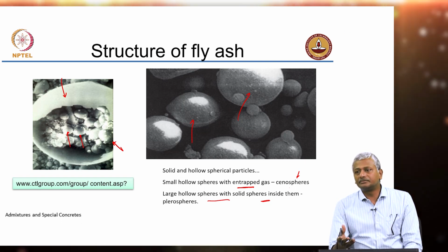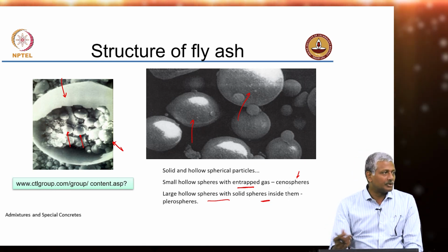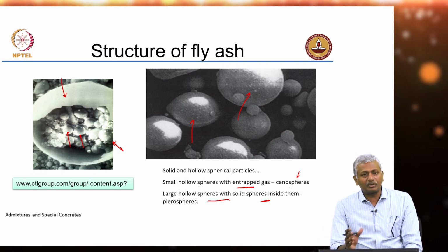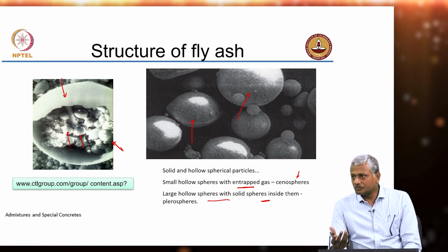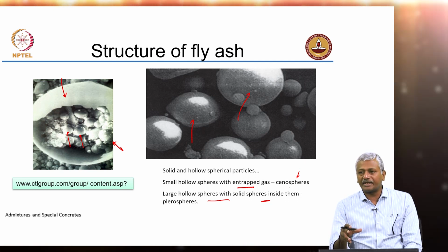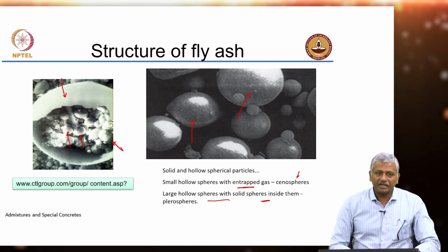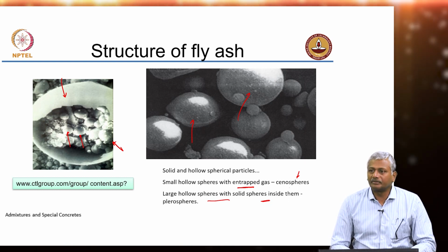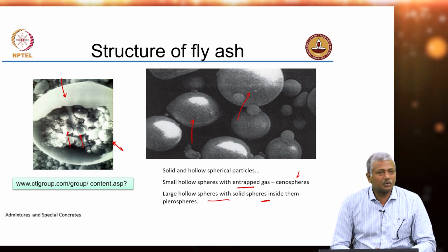What would that do? It would go against your expectation of improvement in workability. It may happen like that, okay. So, you have to be careful about the grinding process. The other route to producing a blended cement is just blending. You can just blend OPC and fly ash, but for that you need to have a well controlled fly ash in a silo. That means you are controlling the composition and fineness carefully, and then simply blending the material together. How will they blend powders? How can you blend powders? You obviously can't blend them in a wet state because cement will start hydrating. What do you do?